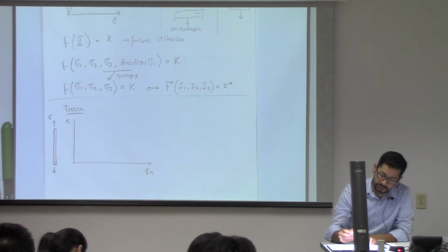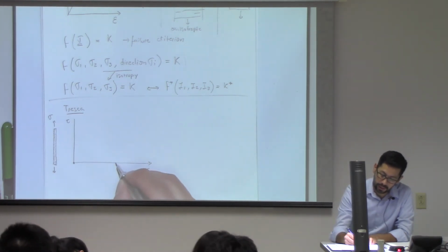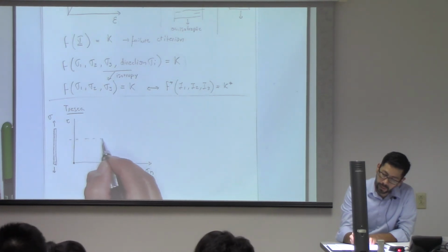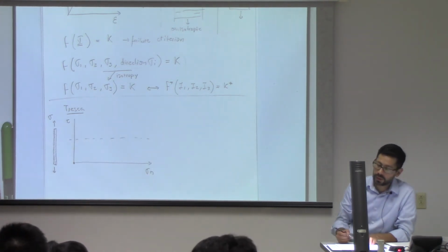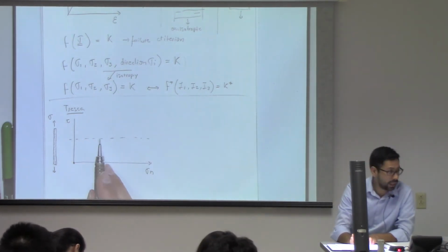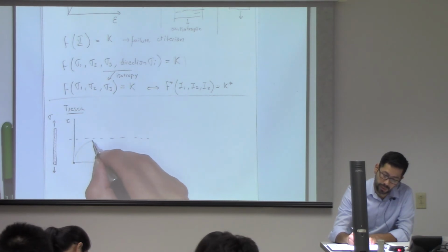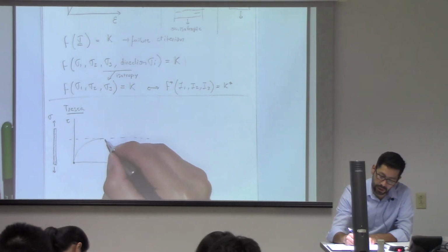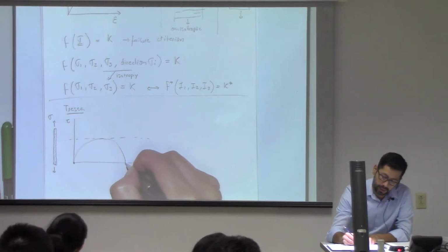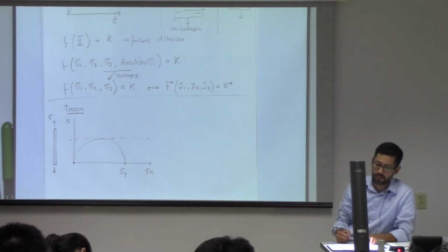If you have no stress from the sides, one point is going to be there, and the maximum diameter of the Mohr circle is going to be given by a limit of this line, in which at failure that Mohr circle touches that line and gets to a value which is the yield stress.